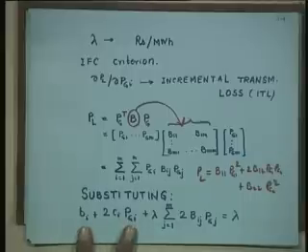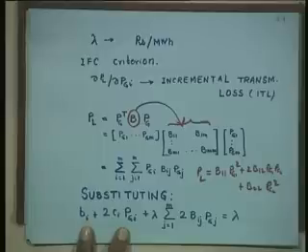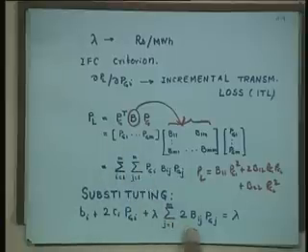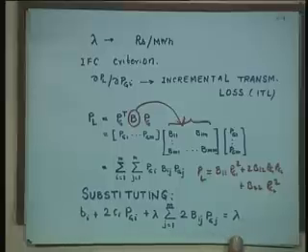Substituting various values in that exact coordination equation, we get Bi plus 2Ci PGi, this is dCi/dPGi. If it is a quadratic cost, you get this. By differentiating, you get a linear equation, the incremental cost curve, plus lambda times, if you differentiate ∂PL/∂PG, what you will get from the quadratic form, 2 times Bij PGj, is equal to lambda. Any difficulty in this equation?